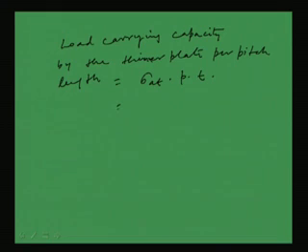So the load carrying capacity is 150 into P into T, where T is 10 mm, the thinner plate thickness. So this becomes 1500 P Newton.